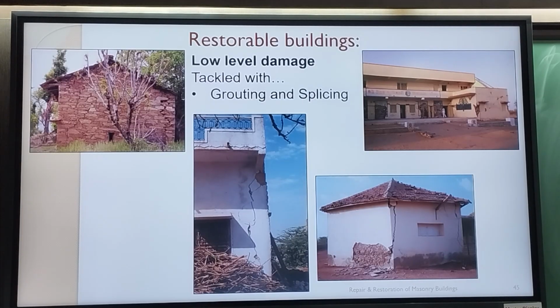In Kutch, there was a major earthquake in 1956. At that time, there was really no understanding, and the government didn't make any effort. This was way back, immediately after independence. Things which were completely destroyed were rebuilt, but the rest was just put back somehow and whitewashed. So those buildings which were damaged then and just restored in some way suffered enormous damage in the 2001 earthquake.